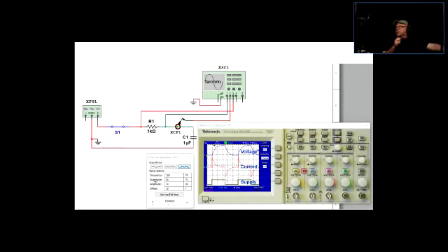And over here, the waveform, I'm not sure you can see it, but the frequency of the power supply is 100 hertz, duty cycle 50, so it's 50-50, amplitude 10 volts peak, and I made an offset of 10 volts.